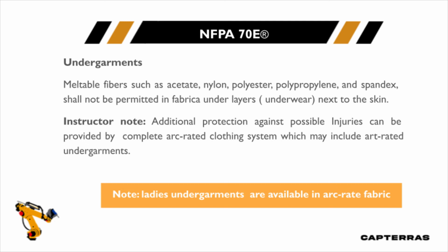The possibility is that those garments might melt to our skin, and we have seen this in the industry. There's one case study that was very unfortunate: a gentleman up in an AWACS plane wearing his Nomex flight suit, which also doubled as his arc flash protection. He was wearing moisture-wicking undergarments, which were meltable. They were not all natural fiber, didn't meet the standard, he didn't think about it that day, and it melted to his skin underneath his Nomex flight suit. So, a year and a half of skin grafts and an honorable medical discharge.